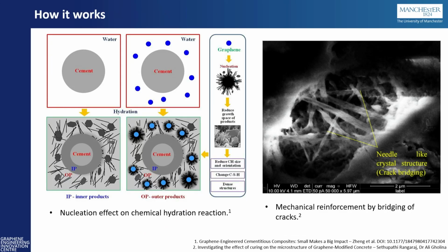Briefly, the mechanism. It's a physiochemical mechanism. It works on multi-levels. Essentially, what your graphene is, is tiny flakes all dispersed through your product with a huge surface area. It's like 2,500 meters squared per gram. It's absolutely huge. And sometimes that graphene can be functionalized, whether we've got oxygen groups in it or not. What that does is directly interacts with your cement hydration reaction. It speeds it up, and it regulates and manages that crystal growth.